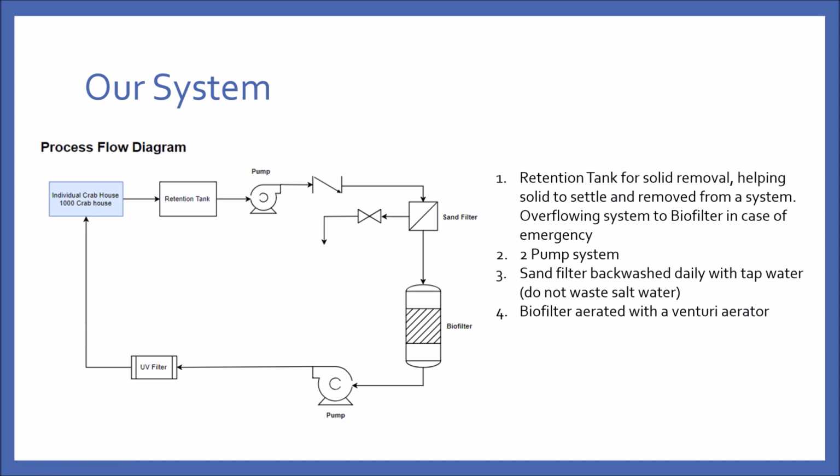Note that we are utilizing a 2-pump system instead of a single pump. And the sand filters are being backwashed daily with tap water in order not to waste any salt water. The biofiltration is being agitated with the pump, and it also has a venturi at the end to perform what we call aeration as well as circulation.